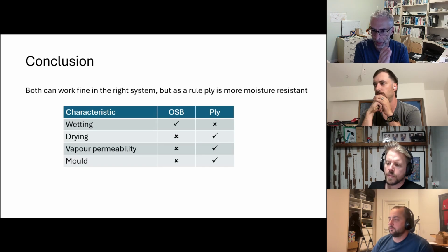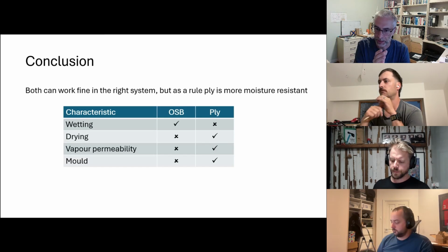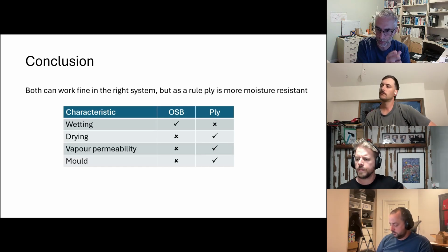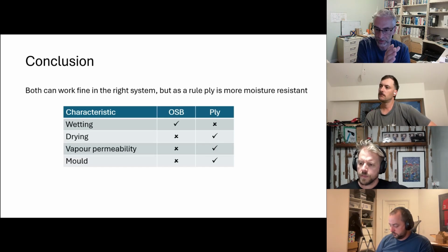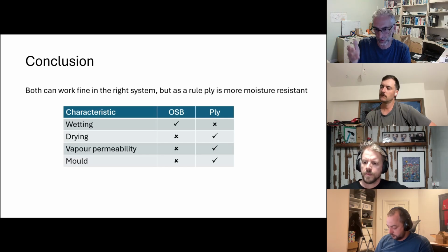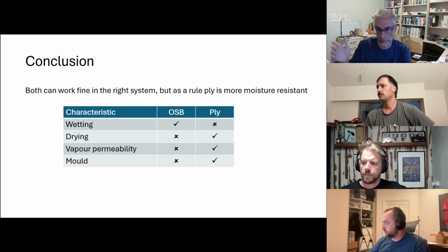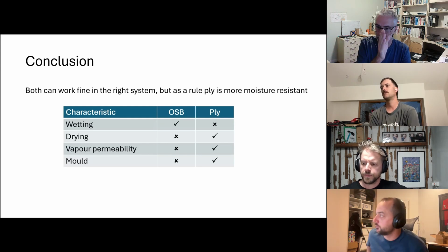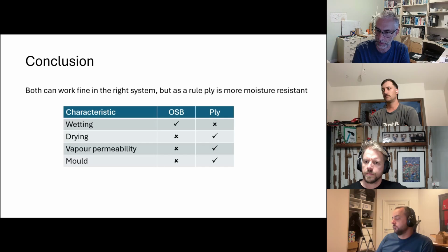And the part that then follows from that is, if you can't make the vapor permeability of the Ply, say, any lower, which you often can't do, in a particular climate, you need a vapor control membrane on the inside of that assembly, which is where we get the talk of all these so-called intelligent membranes, like your Intellos and whatever, that are on the inside of the wall to try and stop that vapor accumulating on the back face of that substrate to start with.